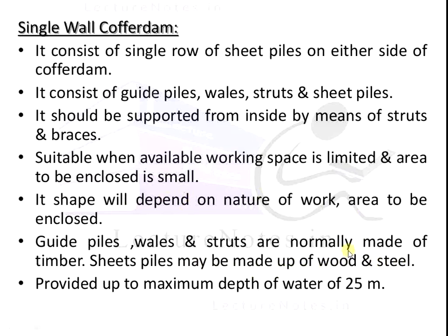For the various materials, the guide piles, wales, and struts are made of timber, and the sheet piles are made of wood or steel. This is provided up to a maximum water depth of 25 meters. This type of cofferdam is used where the depth of water is up to 25 meters.